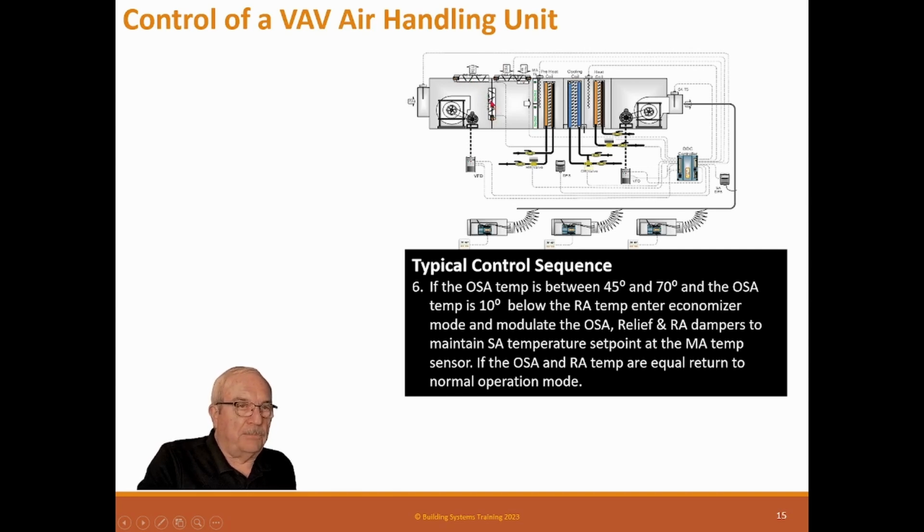Now the return air and relief damper are always the same percent opposite. So they could actually be linked together, but the outside air cannot, because we need it to operate when this is still open sometimes. So basically, this is closed, so all the air coming from the return fan is going out the relief. This is open, so all the supply fan air is coming in from the outside. So now we have outside air doing all the cooling.